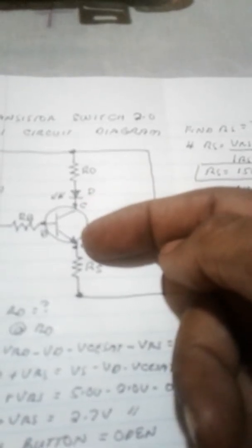Since we are operating with the push button closed, we're now using 0.02 ampere here, the forward current of the LED, passing to the transistor conducting in logic 1, inputting a signal 1 here, conducting the transistor in saturation mode, with a current of 20 milliampere, and the voltage drop of the resistor is 1.15.